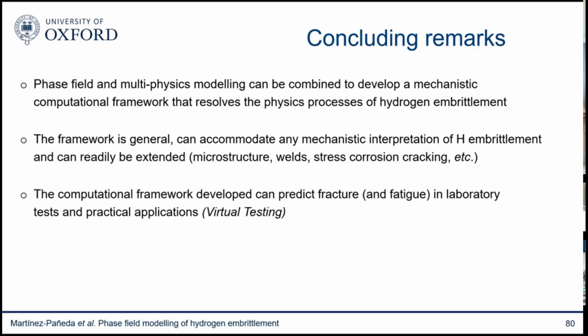I think the one key aspect is that the framework is very robust. It takes only 2 parameters as input, fracture toughness and strength. And it seems to deliver a very good agreement with experiments. But not only laboratory experiments, but also large-scale, real-scale virtual testing of components. Well, we have seen that when we compare them with experiments on pipes and pressure vessels, we seem to be getting a good agreement.